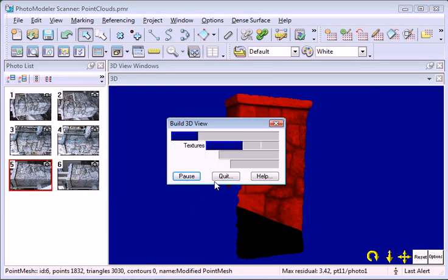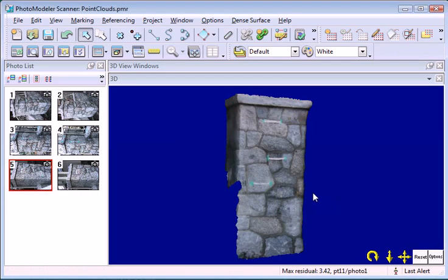Note this project had masks assigned to the photos to mask out the black idealized region when generating quality textures. Generating a quality texture for a large number of triangles over a large number of photos can be quite slow. Where applicable, you should try to use a single photo material instead of the default multi-photo material, as this calculation will be much faster.